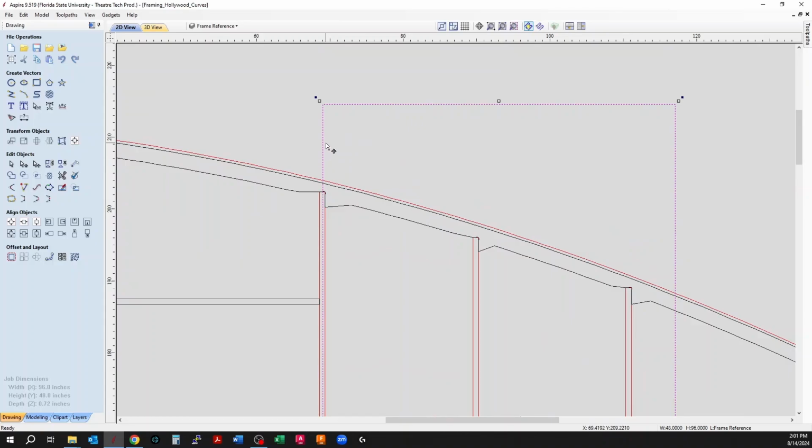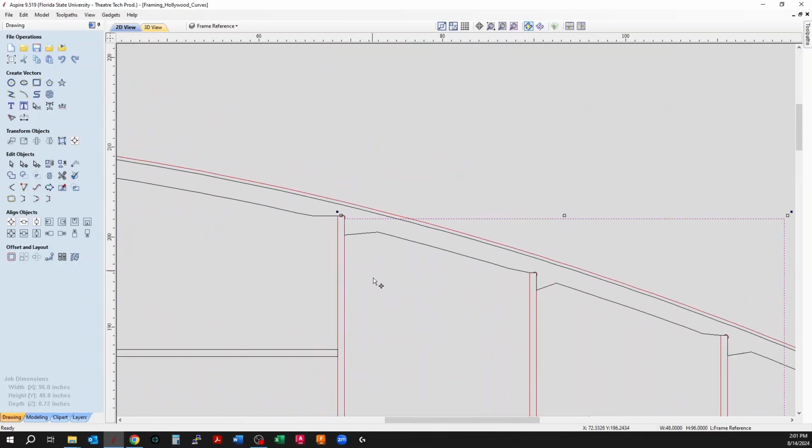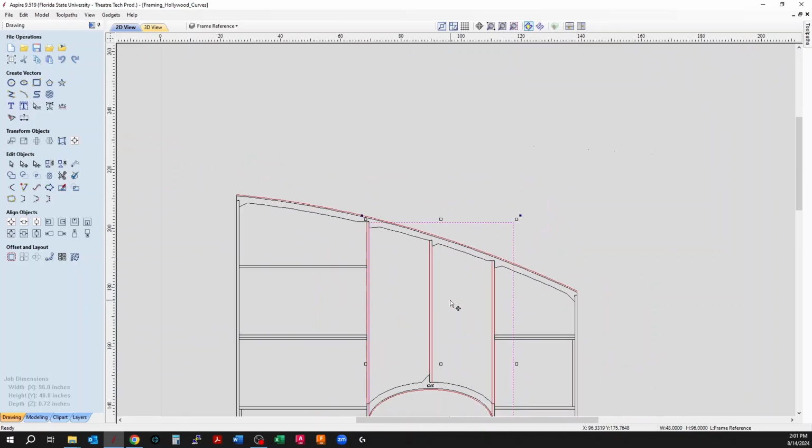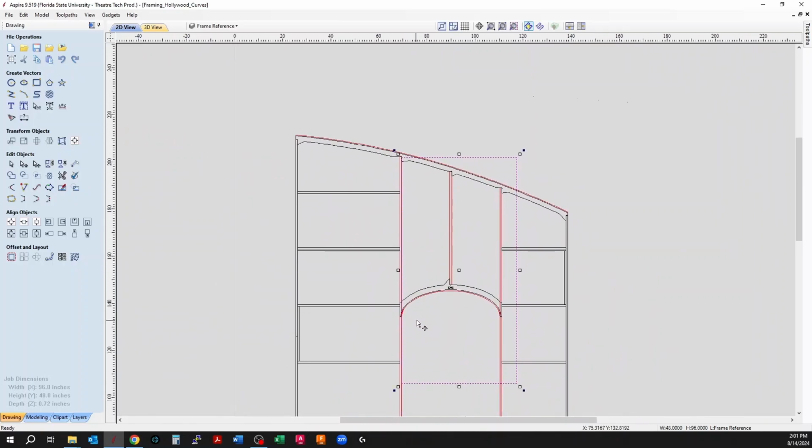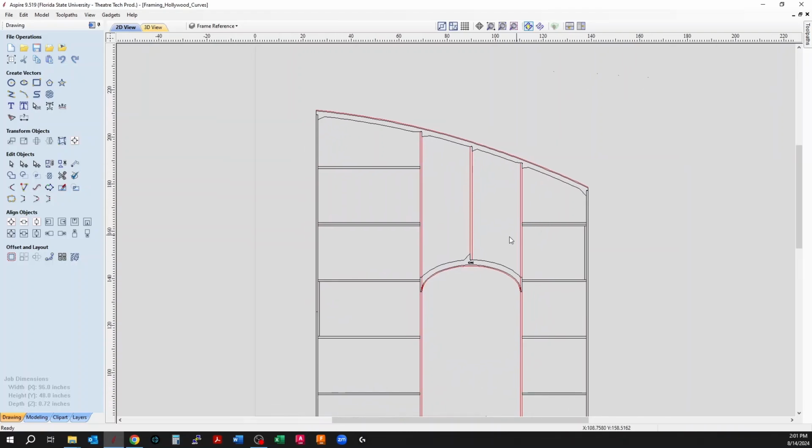So the trick here is that I will need to double up for seam support here, because I've got this seam running all the way up, and then this seam running all the way up, and then so I need in the middle to have those seam supports. So I don't need the sheet anymore. That's kind of not helping me a great deal.